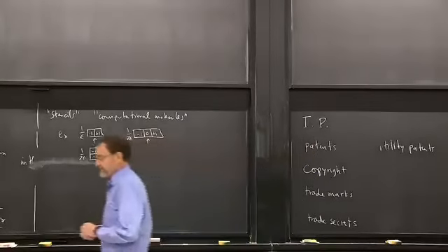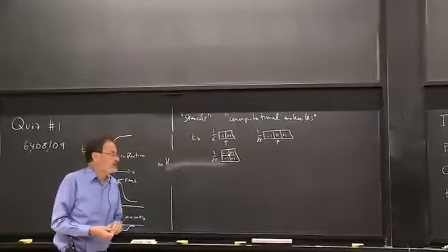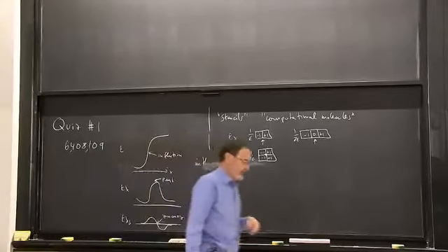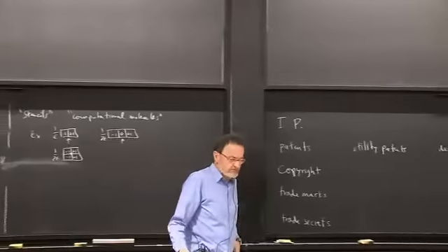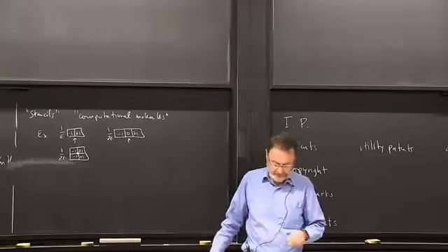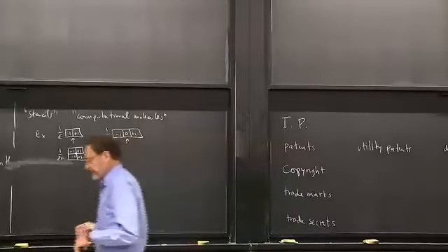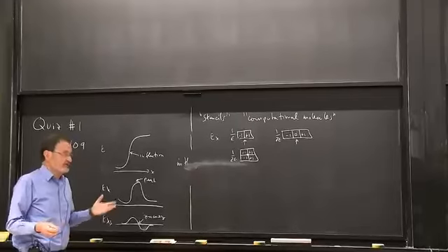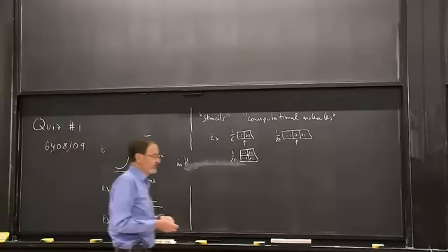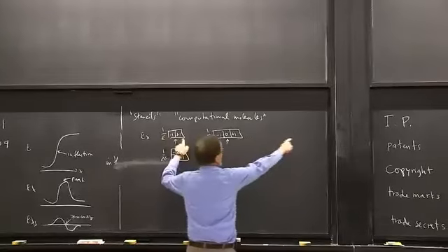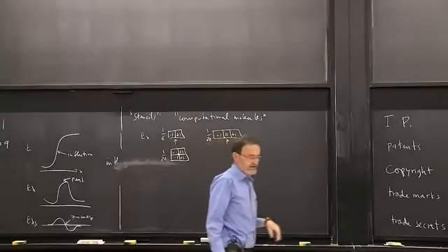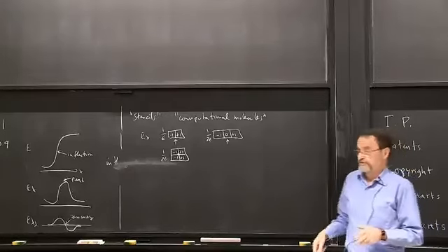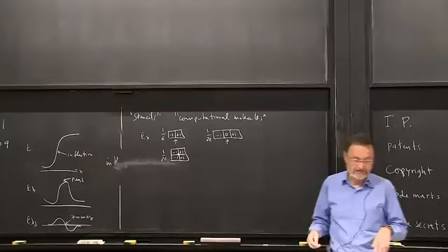So, for example, in analyzing muscle electrical signals, there's quite a bit of noise, and there's quite a lot of distortion of the signal as it progresses through tissue. And so, when people are trying to estimate the first derivative, in one paper I saw, they use a 39-degree approximation. So they use a pattern that's 39 elements long, and they feel that way they can control the trade-off between suppressing the noise and getting very accurate results.